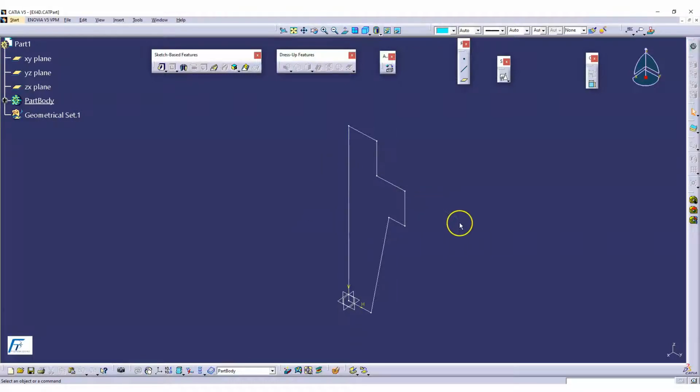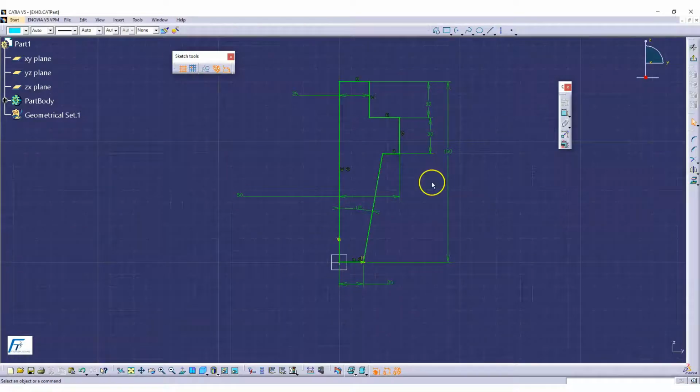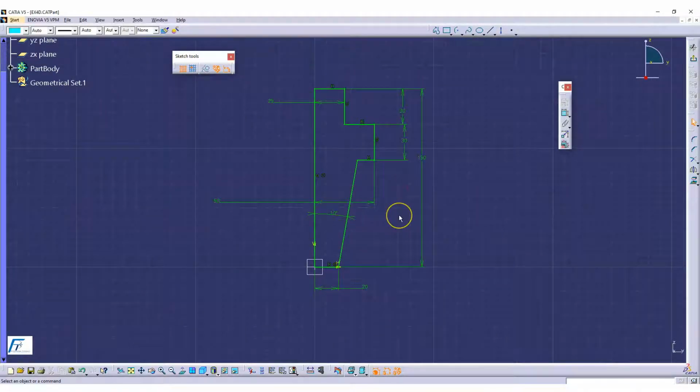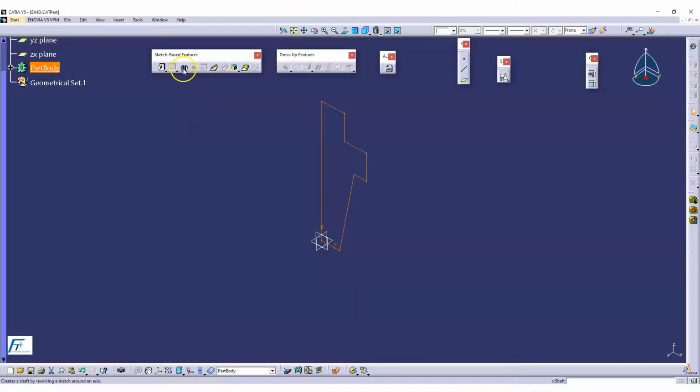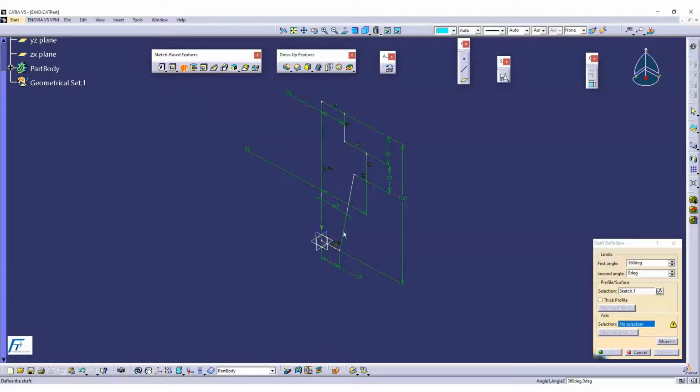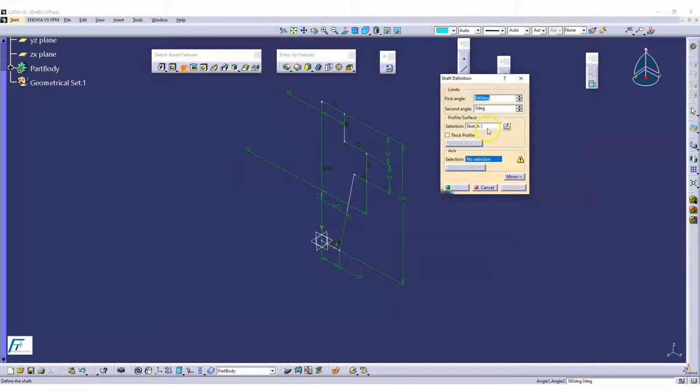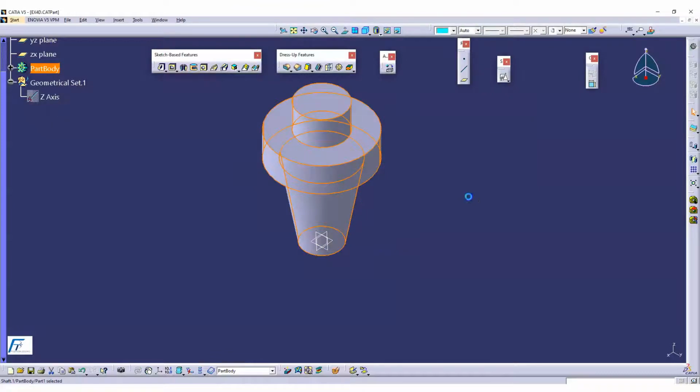So in this case, I'm going to take this sketch and ensure that the sketch is fully constrained. So let me know whether the sketch is fully constrained or not. Perfect. It is. But do you find any mistakes in the geometry or dimension representation? That means, is there any challenge? I'm going to rotate it. I'm going to shaft the entire component with reference to this vertical axis. This is my shaft, this is my profile, and this is my rotation axis. So I can select the axis and rotate with reference to that one. It happens. There is no problem.